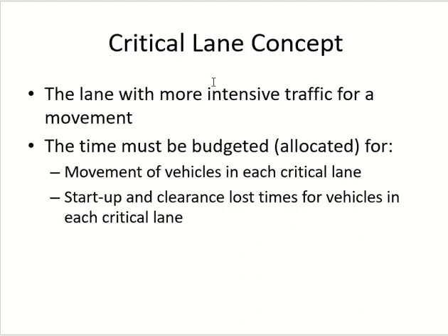That lane is called the critical lane. Okay, the lane from which you will pick the volume and put for VC. Clear? Or put in your design. Okay, so every phase can have multiple lanes, but you have to pick one of them as critical. Okay, and the timing and everything will depend upon that lane.